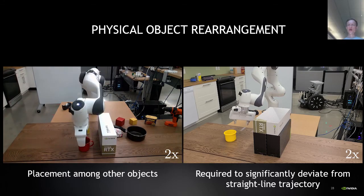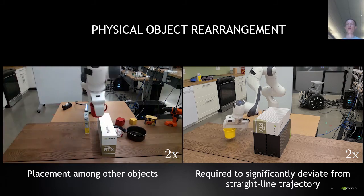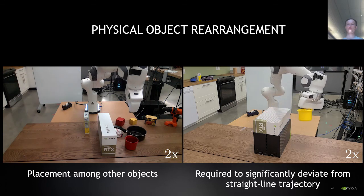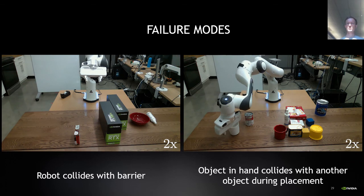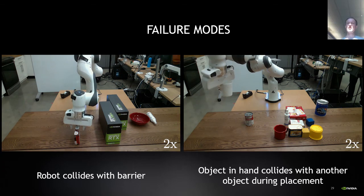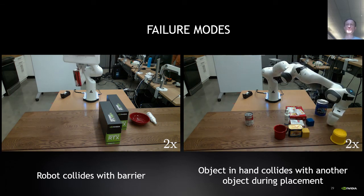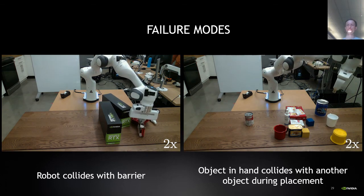We show that the MPPI policy can successfully operate in real-world scenes with noisy point clouds to pick and place objects even among clutter in the placement zone, or when it's required to significantly deviate from the straight line trajectory to the goal. The policy performs very well in real tabletop scenes, but may still collide with the scene occasionally. In future work, we will leverage the continuous nature of our collision predictions to plan more conservative trajectories and also explore new techniques of generating candidate robot trajectories.